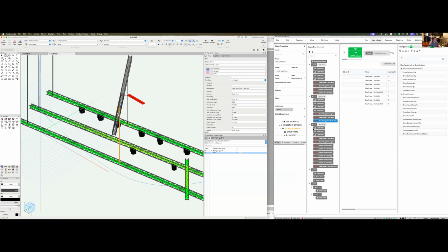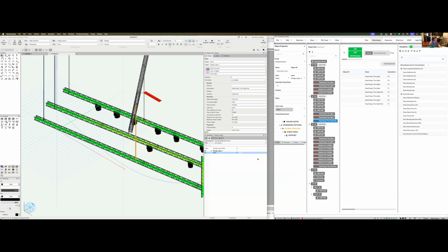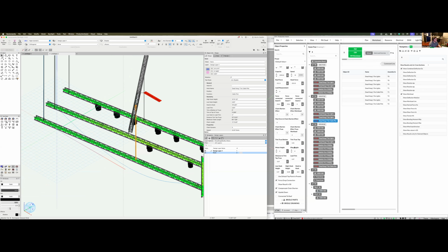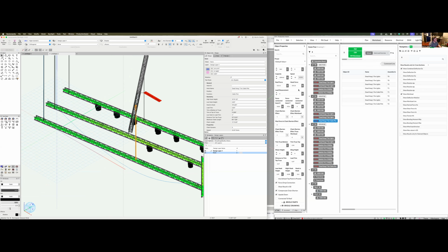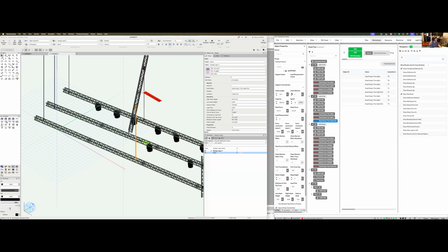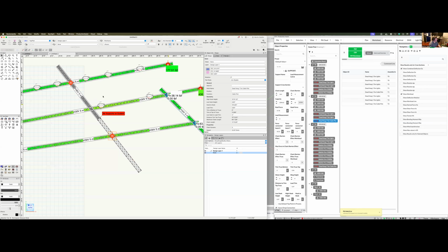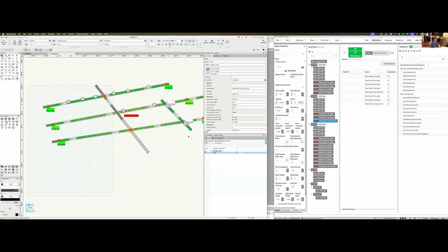For a practical demonstration, select a hoist and adjust its chain shorten value. Then observe the updated load distribution in real time. You can also use the Calculate effect from Chain Shorten command, which iterates through each hoist one at a time to display how small changes impact the overall rig. This function is invaluable for understanding misleveling effects and ensuring that your rig remains safely within load limits.